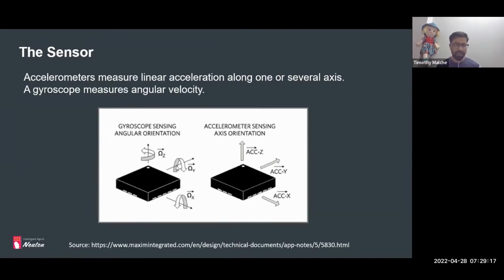Using the accelerometer you can measure linear acceleration, and using the gyroscope we can measure orientation. For our project, you have seen one use case, which is that the shipment is moving. That information we can get through the accelerometer. You have also seen one status of the package in which the package is placed in the wrong position, that you can achieve using the gyroscope.